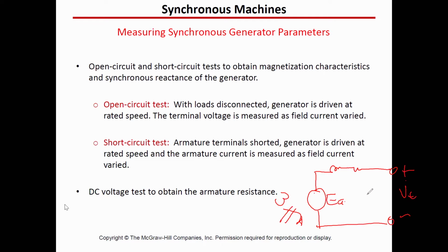Do you agree? There's no current. And we measure the voltage while changing the field current. You're going to do this in the lab today and tomorrow. So you change IF, and each time you record the value of the terminal voltage. This is for the open circuit test.